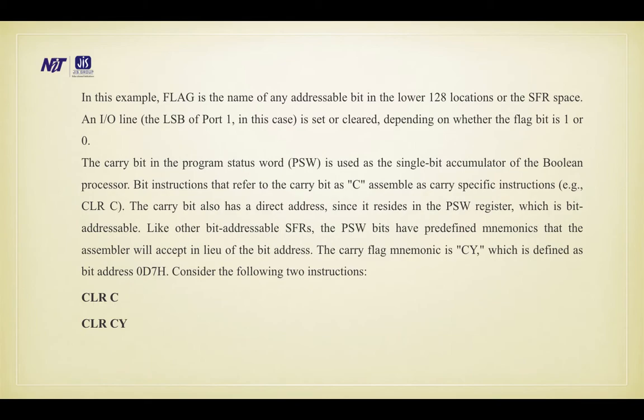So, the carry bit in the program status word is used as the accumulator of the Boolean processor. The carry bit also has a direct address, and this is shown over there: CLR C, CLR CY. CY defines bit address D7H.